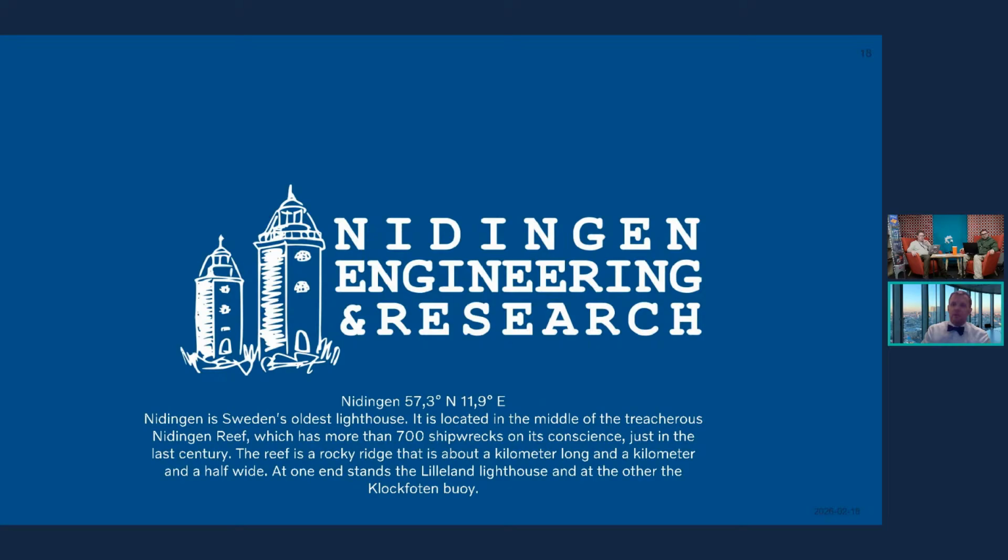Then my colleagues responsible for control system development can start thinking about strategies to control and optimize the system, minimizing the energy consumption of the thermal system while it performs its task of keeping the battery typically between 22 and 28 degrees and the cabin around 22, already very, very early. So in the simple library there's a lot of information I don't need, which allows me to start much earlier than I otherwise would have been able to.